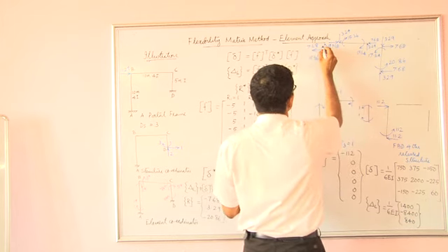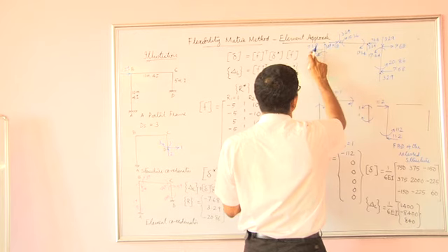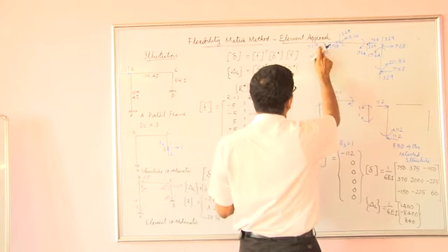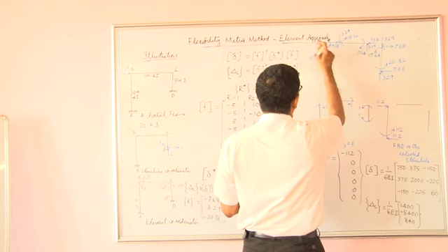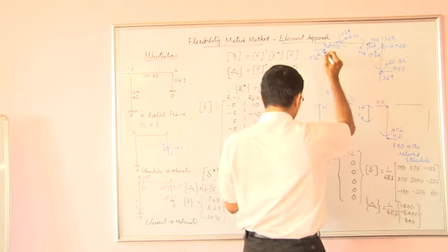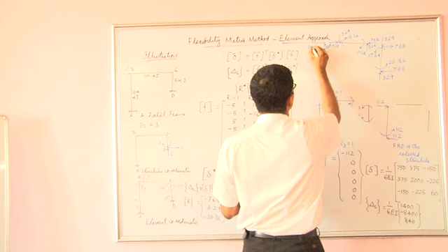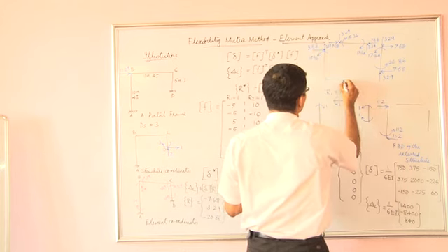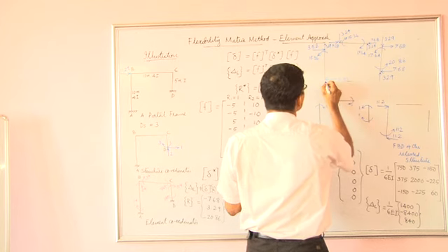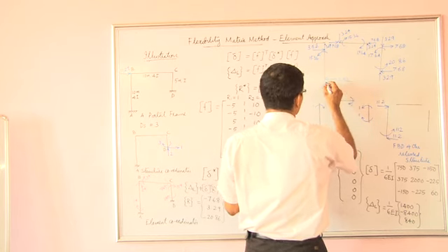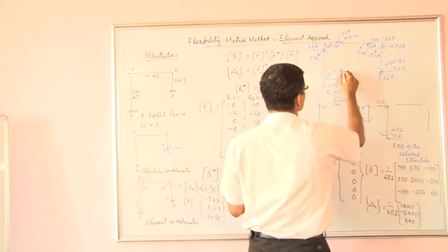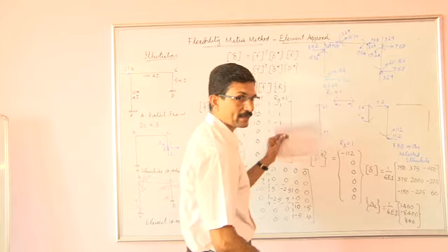So that is going to add to this with a minus sign, and the result of the 7.68 to the left, 11.2 to the right would be a rightward force of 3.52. This force is 3.29. And the moment here would be 19.84. So bending moments at the joints are available, and we can draw the bending moment diagram.